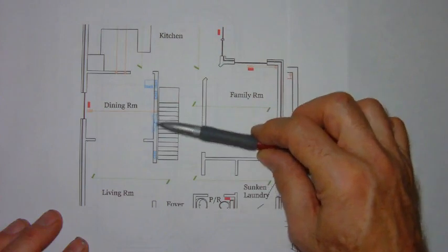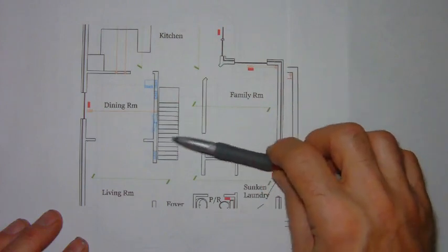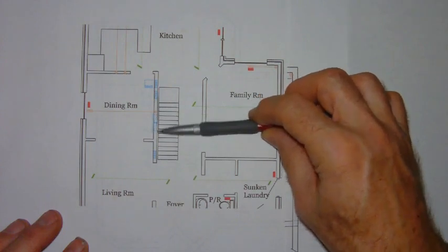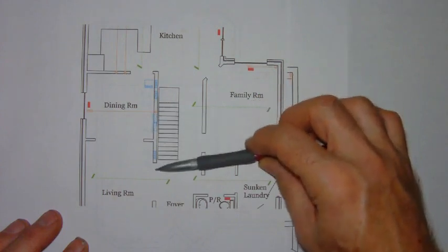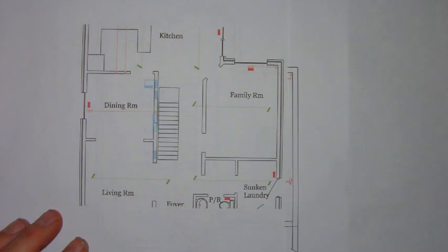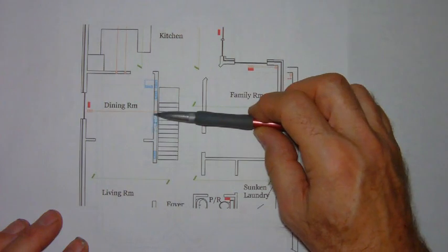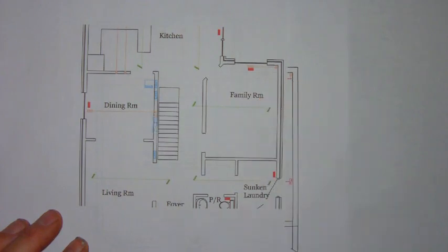So although our calculation suggested 3, because we've got 2x6 partitions here, I am going to suggest that we start with, in this case, 2 plate openings, which would be equal to perhaps a 30x6 or a 30x8 return air grill.